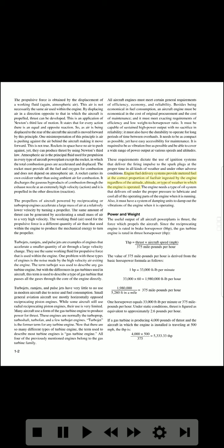Engine fuel delivery systems provide metered fuel at the correct proportion of fuel to air ingested by the engine regardless of the altitude or type of weather in which the engine is operated. The engine needs a type of oil system that delivers oil under the proper pressure to lubricate and cool all of the operating parts of the engine when it is running.